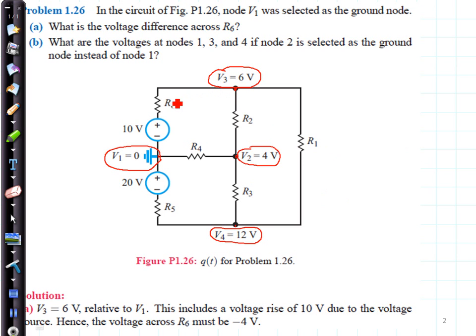All right, now we would like to know what voltage drops we have across each of these several resistors. The way we do that is we start out at a voltage and we just calculate down to ground like this. We're going to write this voltage, and I'm just going to guess that its polarity is probably in this direction. It doesn't matter. If I guess wrong, I'm going to get a negative number, and that's okay. So we start out with our positive voltage, so we say 6 volts is equal to, and then what did I hit first as I went through this?